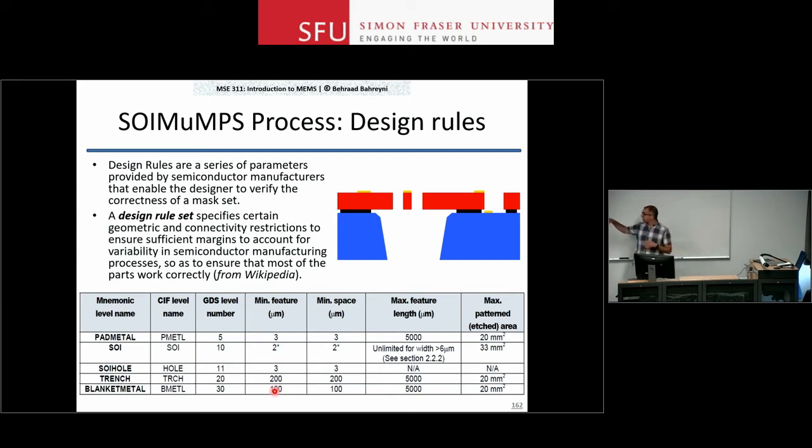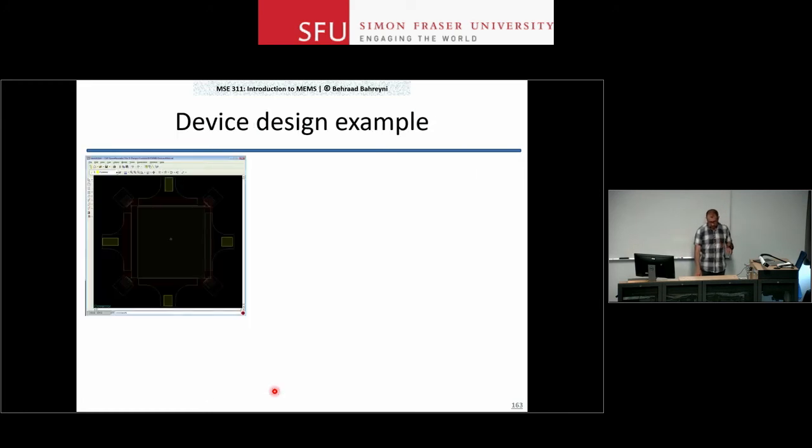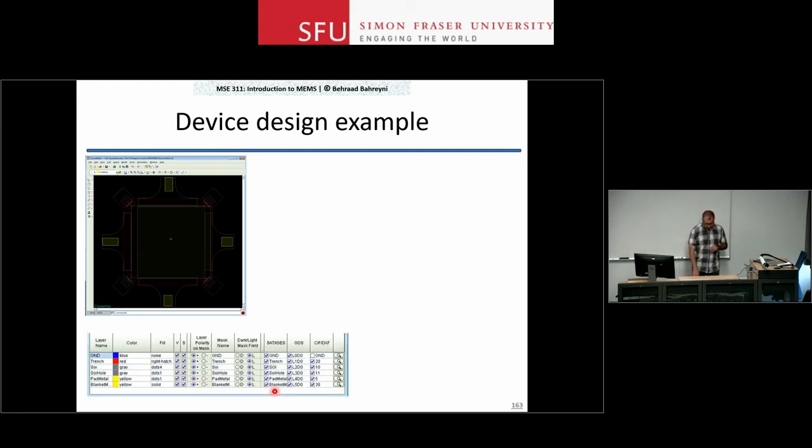So anyway, as a MEMS engineer, it's best if I know how the processes are done, and I have enough education to figure out the limitations of these processes. But what I can work with is this table of design rules. And then what I do is design, making sure that my device doesn't violate any of these design rules. So this is the layout of my device. At the end of the story, I make sure that everything is where it is supposed to be.